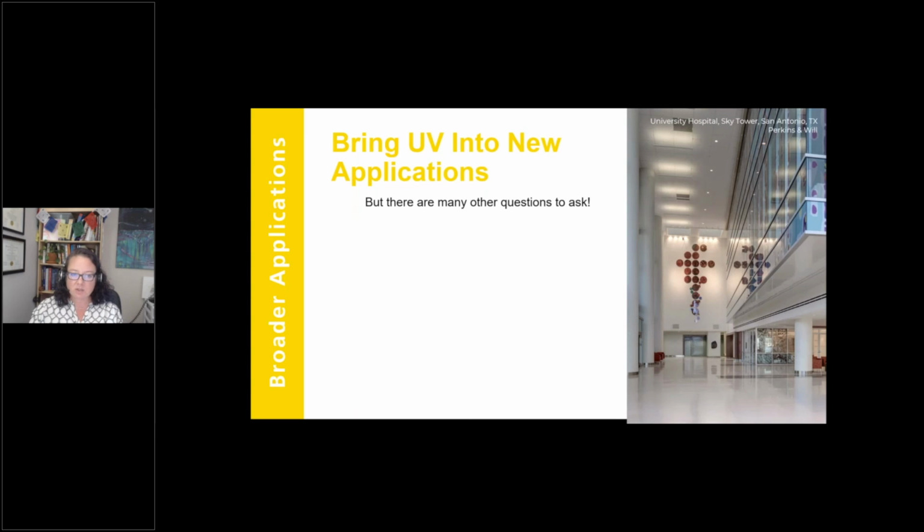But as we start to stretch the broad scale application of UV to many more parts of our built environment, we as designers have some critical questions to ask. First, how do we as designers calculate UV applications so we know how many fixtures to use, at what spacing, and at what height? UV output of a fixture is not captured in photometric reports for obvious reasons, as Dave talked about, so it's a whole new data set. And when you bring in the issue of surface reflection, which really isn't well known or quantified for UV, how do we effectively calculate our applications?